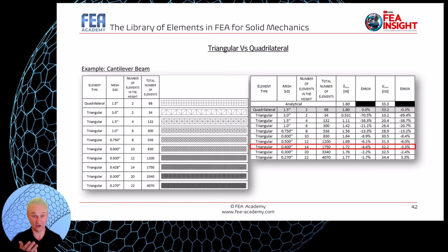And it is what I did and what I present here. The beam has been meshed with triangular constant strain elements and fully integrated quadrilateral plate elements of various mesh densities. The table here summarizes the different mesh configurations.